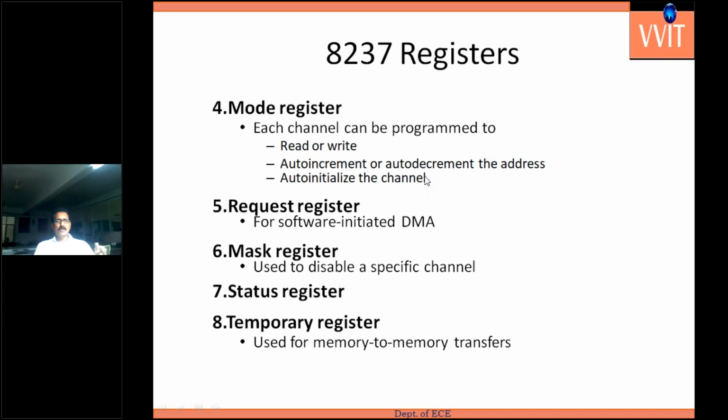Next, the mode register: each channel can be programmed for read or write, automatic, auto increment or auto decrement address, and auto initialization of the channel. Then the request register for software initiated requests, the mask register, the status register, and the temporary register for memory to memory transfer.